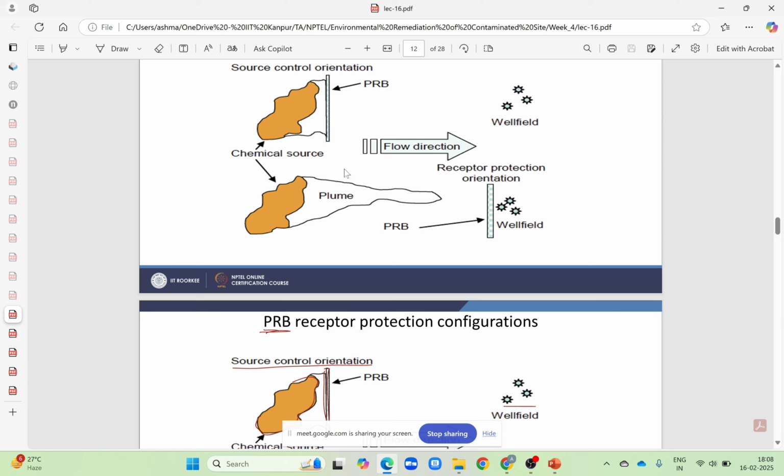And slowly, with time, when the concentration of the pollutant decreases with pumping the groundwater, then this pollutant will again dissolve in the liquid aqueous phase and try to achieve equilibrium. And that's why we see tailing and rebound in the case of pollutants which are present in different phases in the aquifer.